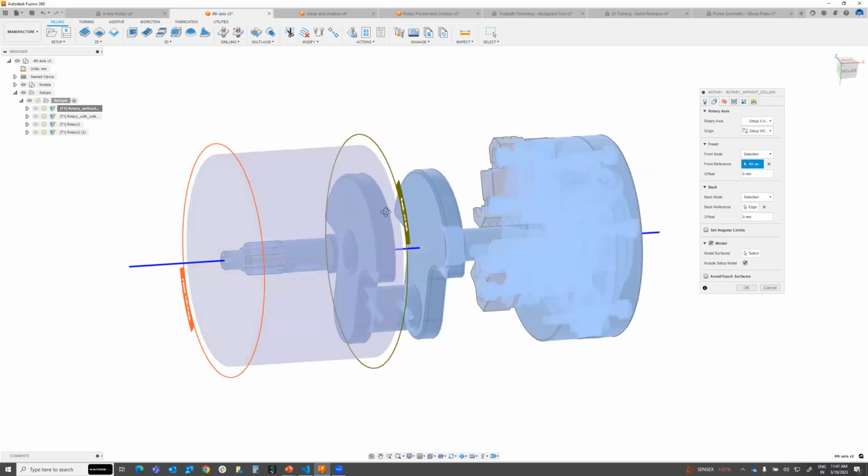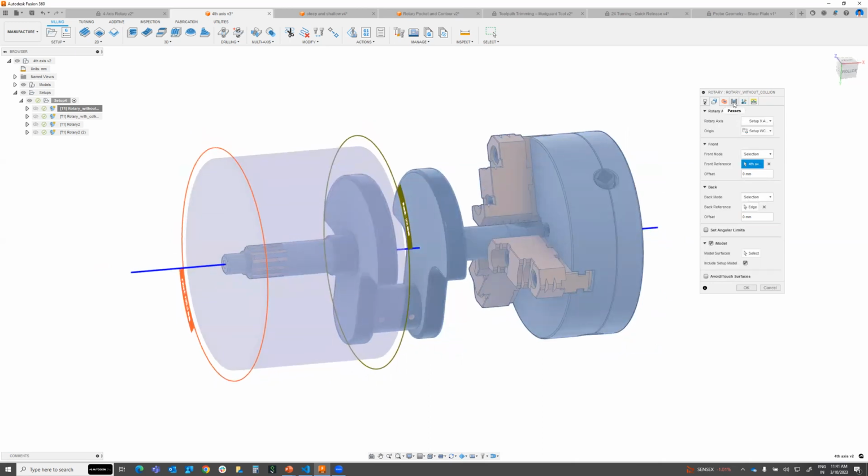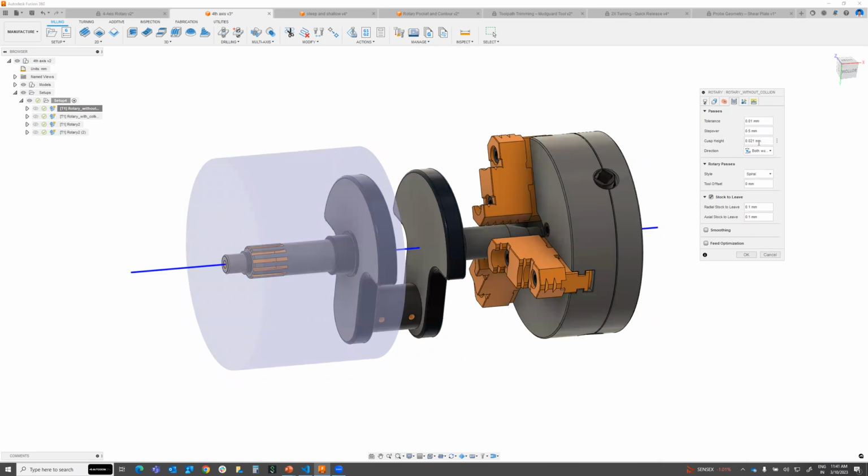Then the second is from this point. Once you select, you can go to the toolpath you want to do for one-way or two-way cutting. Select both, and here there are three options that I explained in the PPT: spiral, line, and circular. Suppose I'll use the spiral one.